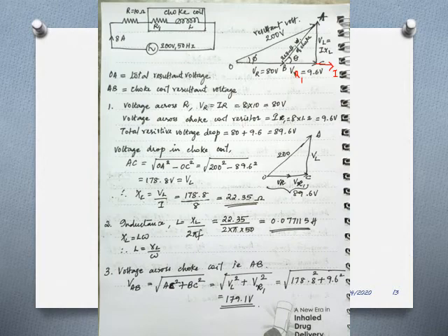Well, the values of the choke coil, I have taken as R1 and L. So the entire elements are connected across 200 volt 50 hertz, and a current of 8 ampere is flowing through this circuit. So this is how you draw a circuit diagram. Now coming on to the phasor diagram. The phasor diagram is a bit more complex than the previous problem. So kindly pay attention. First, let's draw the phasor diagram of the choke coil.